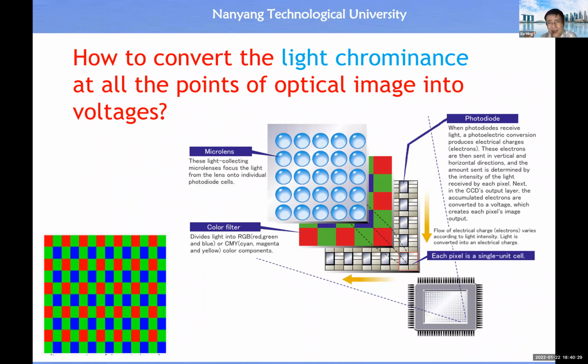So the current design guideline is 2 photodiodes are dedicated for the green color component, 1 dedicated to the blue color component, and 1 dedicated to the red color component. This is the current practice, and you can always ask why not allocate this one to intensity sensing, so then we will have a perfect solution. So this is a solution.